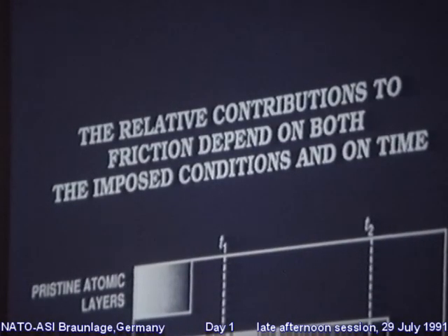Right. Now, I say the relative contribution to friction depends on both the imposed conditions and on time. So if I'm going to use another schematic viewpoint of things, perhaps when we have low normal load or low contact pressures, we might be able to sense the effects of pristine atomic layers, or perhaps even initial surface contaminants that would swamp those effects.